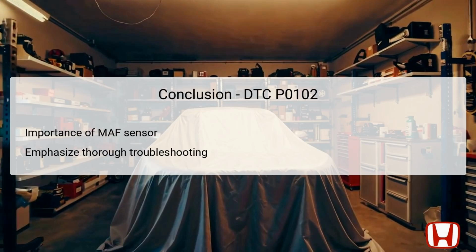In conclusion, the mass airflow sensor is vital for ensuring the proper air-fuel mixture in Honda Accords from 2012 to 2017. The DTC P0102 indicates a critical low voltage issue requiring careful troubleshooting. Each step, from inspecting wiring and testing voltage to replacing the MAF sensor, builds upon a clear strategy to restore engine function.